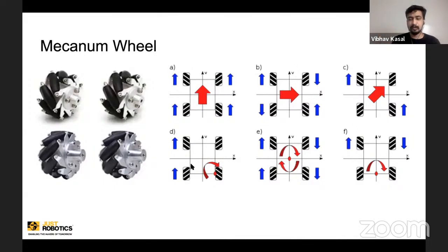So now this robot can also turn around its axis about a pivot point. It can turn around an axis situated at the center, the contact point of a wheel, or a midpoint. The pivot can be at the midpoint when it is rotating, or in between the 2 wheels. But the thing is, here you are independently controlling each of the motors.